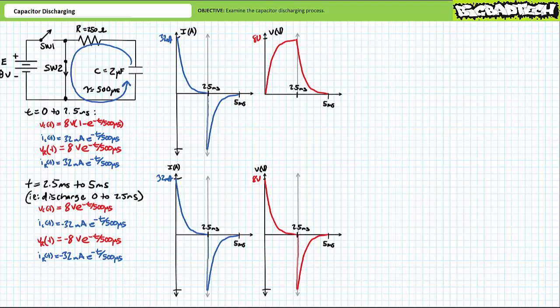Current during the charge and discharge phase are equal in magnitude, and a full charge takes just as long as a full discharge. Finally, you will note that the resistor in the symmetric charge-discharge circuit experiences an interesting phenomenon, that of alternating current and voltage. During the charge process, current and voltage appear left to right. During the discharge process, current and voltage appear right to left. If we consider only the mathematical average, one might be led to believe that on average, the resistor experiences 0 amps and 0 volts, thus 0 watts of power. After all, we're presented with equal and opposite magnitudes of voltage and current for identical durations.